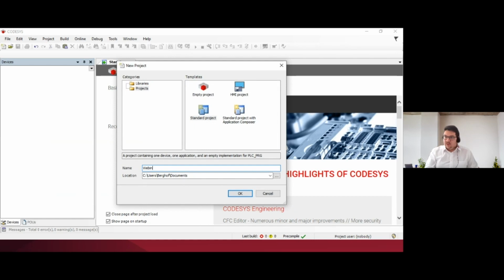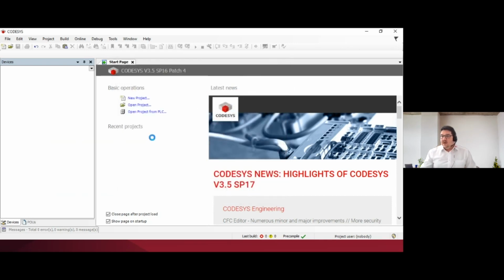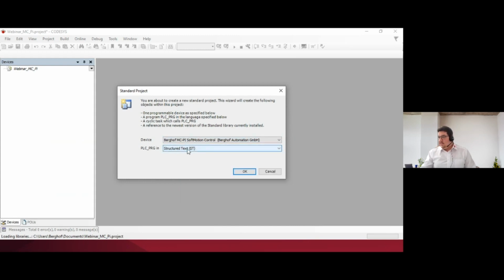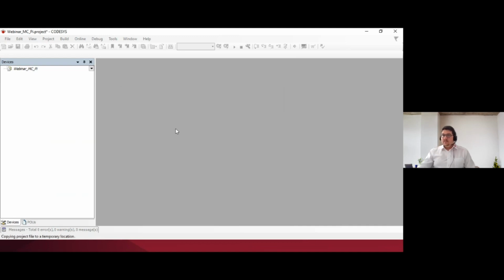Let's just call it Webinar MCPI. The location is, of course, always a use case. I say OK. And now here in the device, I can select my Berghof MCPI and my main PLC_PRG for my main program call.